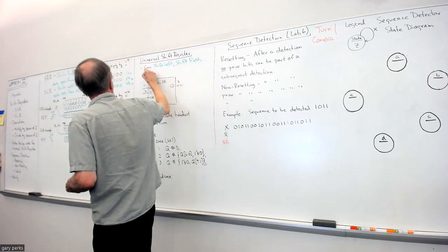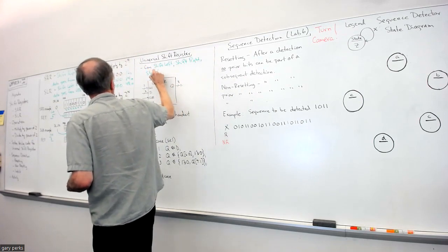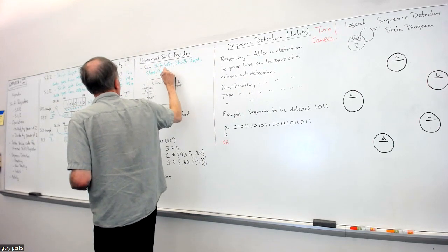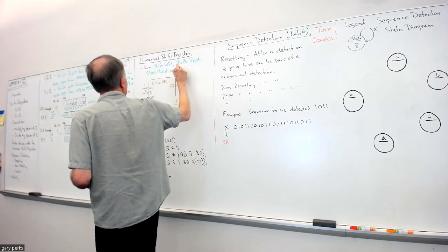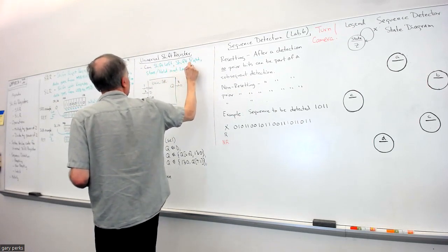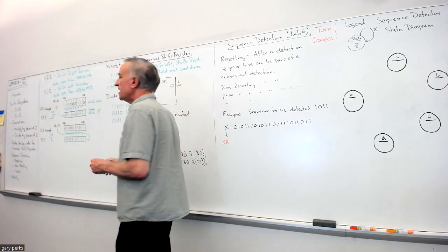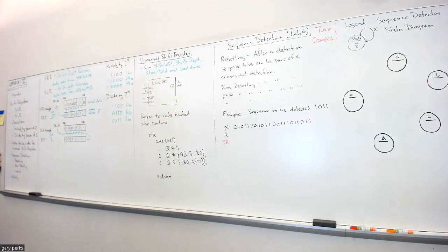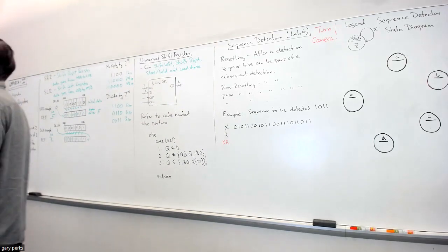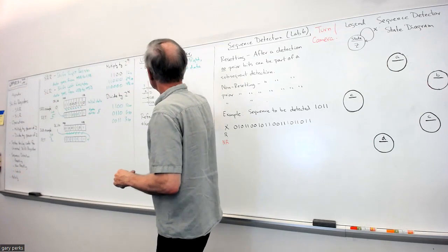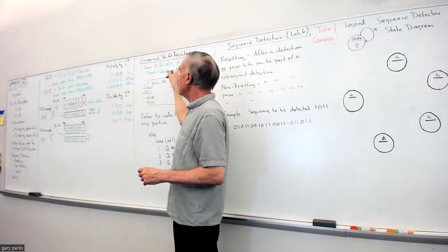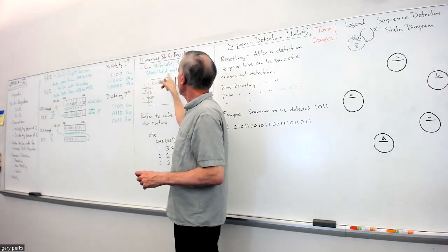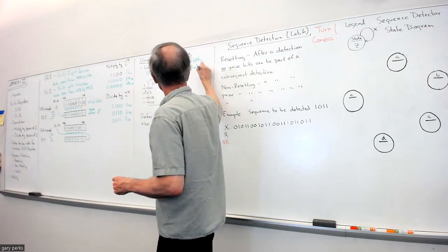It can also store, hold, and it can load data. And when I say load data, that's the same as a memory register when Q equals D, right? When we update the Q outputs with whatever's on the D input. So these universal shift registers can shift either direction, they can store, and you can load data too.